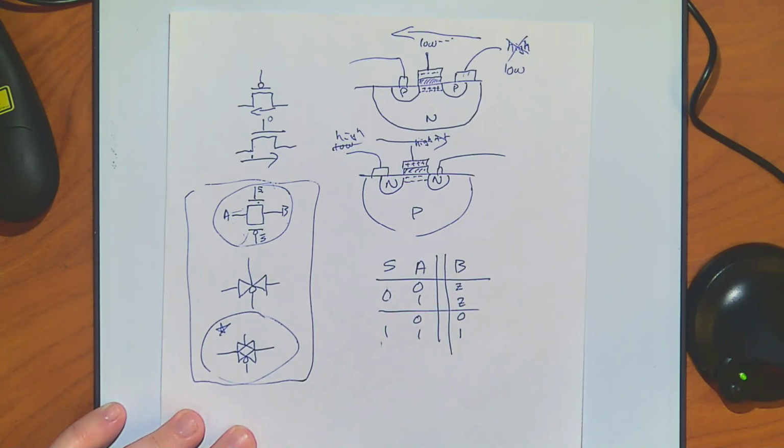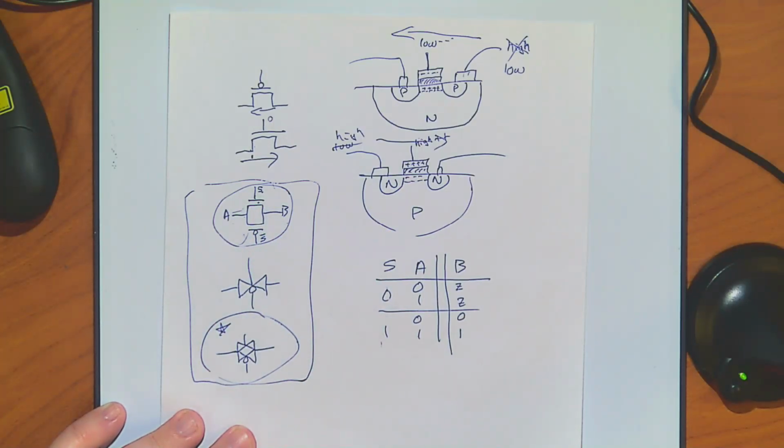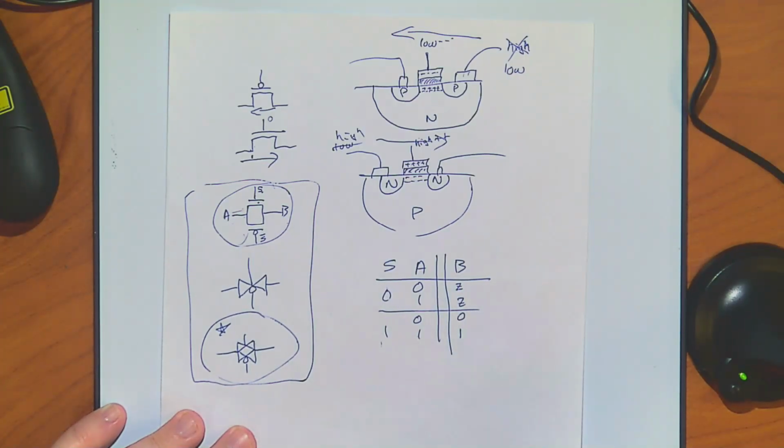So we now have a transmission gate, such that as long as you make this S and S bar on the dotted side, when S is low, it shuts off, and when S is high, it just passes through. And since both of them are pretty optimized, it'll pass through really well. You will not get much of a drop. It doesn't weaken the signal a lot. So you can pass quite a few of these through cascaded.